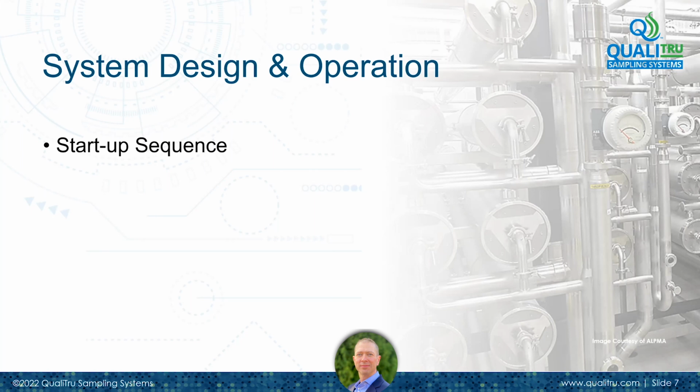So when the process stream tries to maintain the flux going from water to product, it'll probably start really hard and then fall back with a lot less permeation than if you kept it on a leash to start with. Setting up the automatic sequences in draining water on incoming tanks or different parts of your system, using indicators like inline sensors or hard coded timers in controls programming, can really help on optimizing that potential issue of fighting dilutions. And that can happen for hours as you try to get up to a concentration factor if you're concentrating at a high VCF.